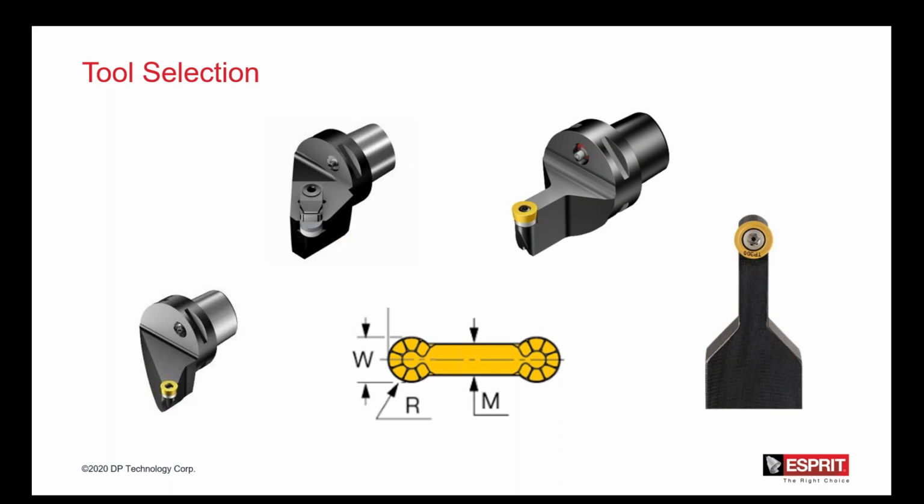These round inserts also do a great job with your harder materials, your super alloys, Inconels. The profit turning cycle is actually designed for those hard materials. That's where a lot of the advantage comes in. You can still use it for your softer materials as well. With standard tooling and standard traditional tool paths, there's not too much of an advantage with the softer materials. But if you're having issues with tool breakage with those softer materials, this is another great way to control chip breakage and controlling that engagement angle. So whether you're cutting soft materials or harder materials, the profit turning is really great for both.